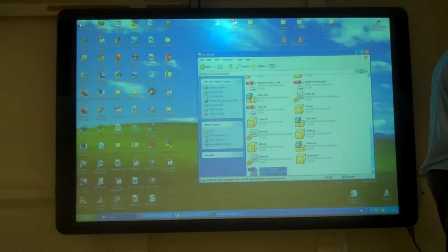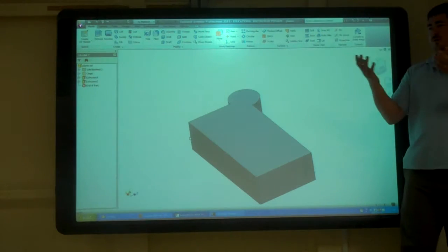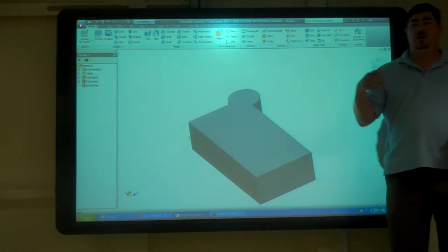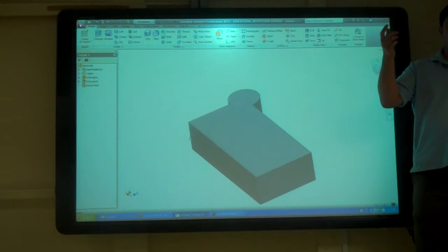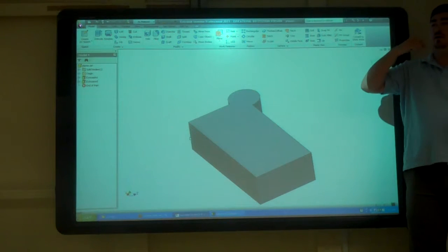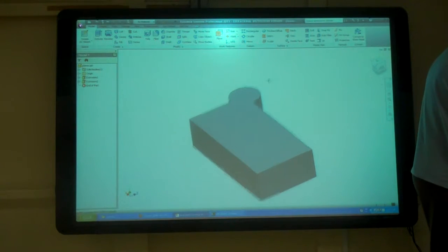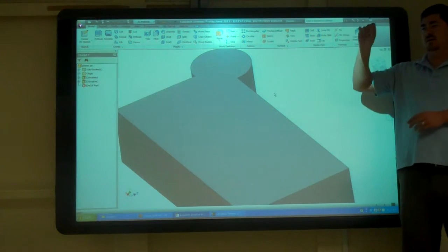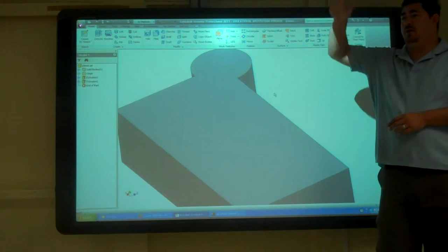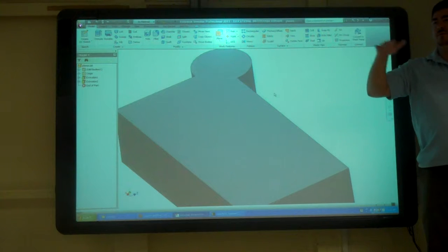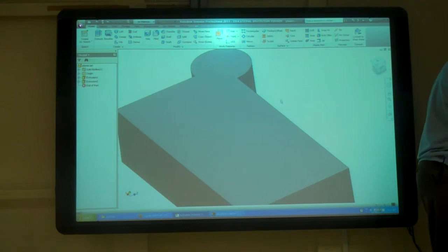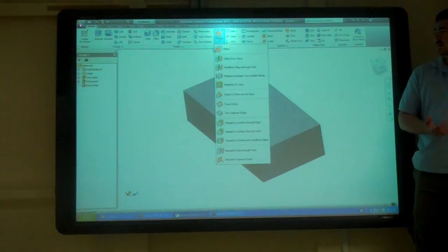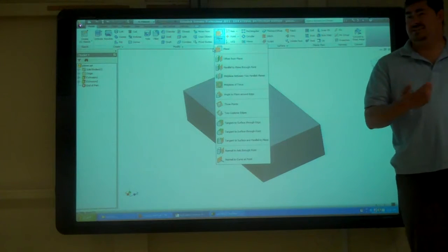And so, kind of do that, there's different ways we can do it. So in order to measure the distance, we can actually take this plane and pull it down or pull it up. And also when you go to extrude or you make a hole, there's the "to" option. You can tell it to go to a plane. So you can have a plane go down and extrude down to that plane. So if you need to move that distance, instead of going into that extrusion and changing it, you just move the plane. And now that plane will be able to line up a few different things. So if we go to plane, those are all different ways to make a plane. It looks like a lot, but it's all basically the same type of thing.